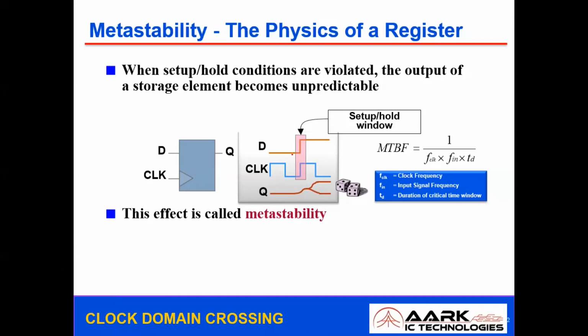So this one is the timing window. It all depends on your clock frequency, how your data is changing, the frequency of your input, and at the same time, what the duration of the timing window is. Based on this, we define the mean time between failures.